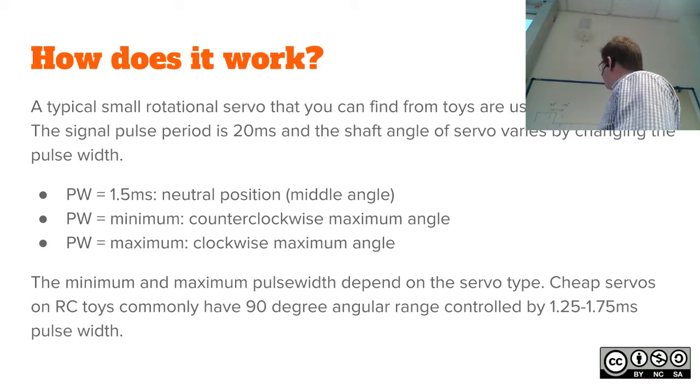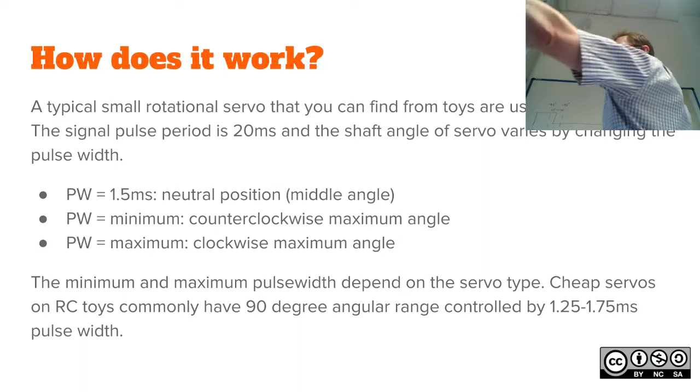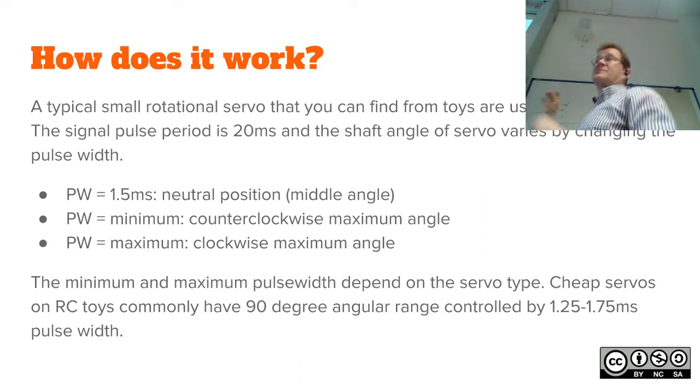Okay. And the full period must be, say, greater than 20 milliseconds, but it cannot be 1 second. Then usually the servo doesn't do anything. But around 20 milliseconds, that's fine.